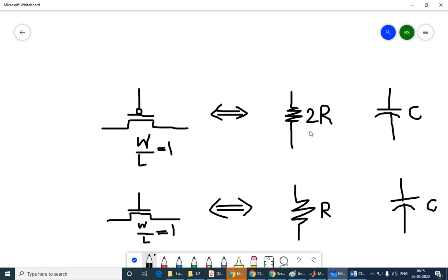This is not uniquely defined, and the reason is associated with the charge carriers. In the NMOS transistor, electrons are charge carriers. It's easier to move electrons, so the per unit resistance is small. So if I apply a voltage across these two terminals, I will get some current here, and here I will get a smaller current, and the reason for that is it's not as easy to move the holes.